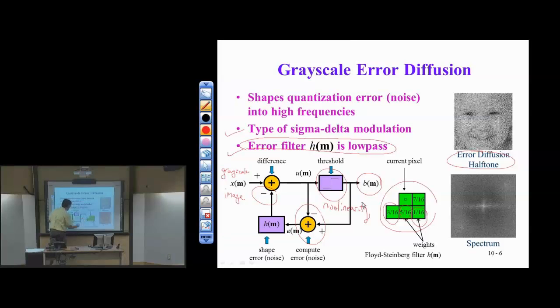But it turns out this quantizer can be linearized, approximated as a linear function, by the following idea. If I have a quantizer, and in this case it's going to give me one of 2 levels, and again, in practice it's +1 and -1, so I have x coming in, and here's my quantized output. I can approximate this over a region as a line.